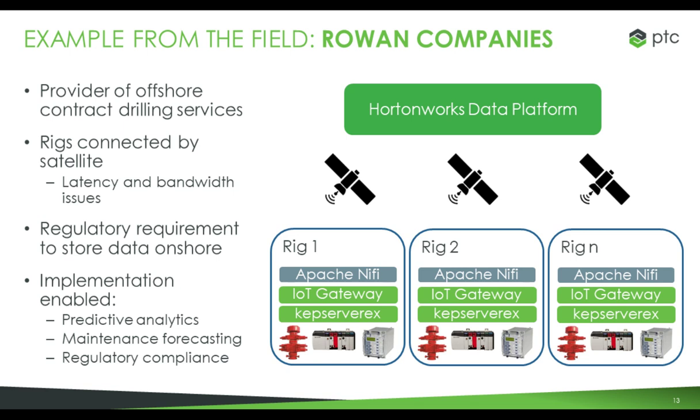And there's ways to do that. And it's always better to collect less data than more. That doesn't overwhelm your hardware or your network, but at the same time, it gives you a focus, because you don't want to end up having to look at a trend chart of 100 different data points and not really having a direction of what improvements it is you want to go after.